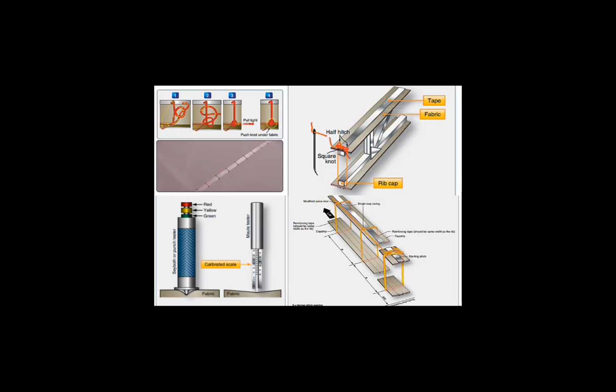What is the purpose of reinforcing tape? Used under all stitching and prevents the stitching cord from tearing through the fabric. What type of fabric is not affected by moisture or mildew? Fiberglass fabrics. What methods are used to check the strength of dope fabric? Fabric punch test, Mullen test.